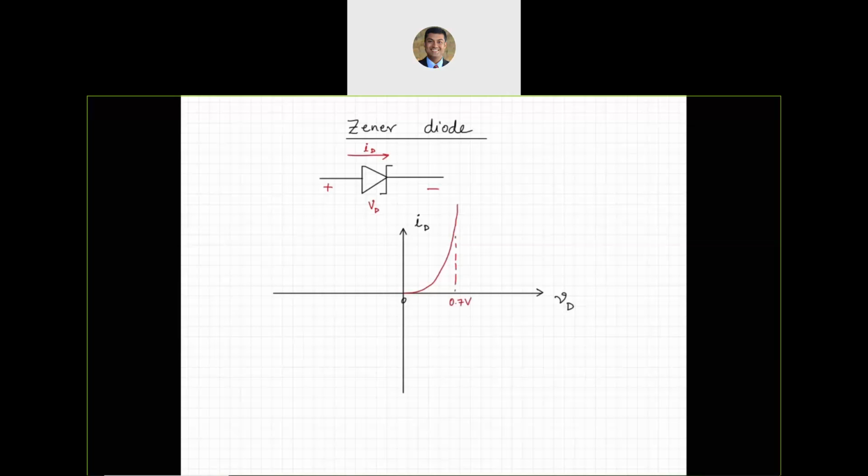However, in the reverse biased region, we know that when we apply a negative voltage to the positive terminal of the diode, we are going to have almost no current flowing through the diode. Only a little bit of saturation current flows during that time. So what I can do is indicate that by perhaps taking a line going there.